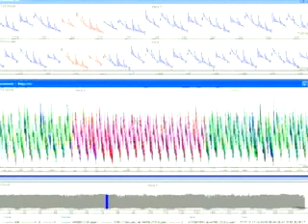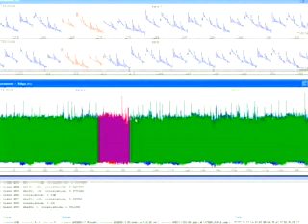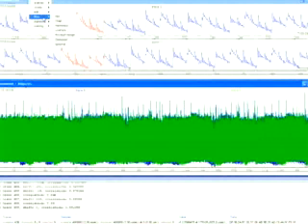So the next step is, because this is a lot of data, each trace is about 400,000 samples, I think. Yeah. Which takes a lot of processing, which we don't want to bother you guys with. We're first going to compress each trace just by resampling. So we're actually going to represent every clock cycle by one sample.